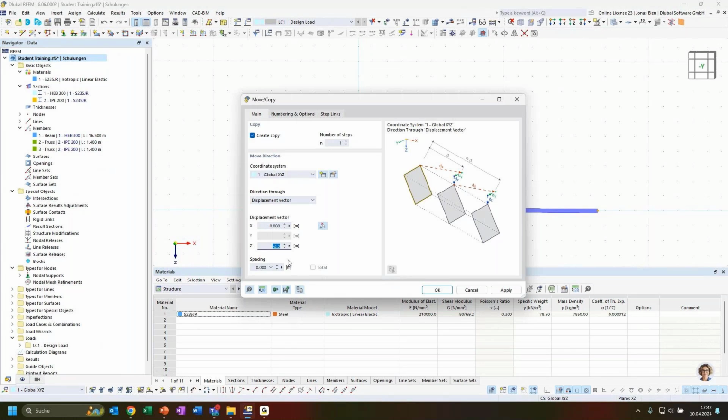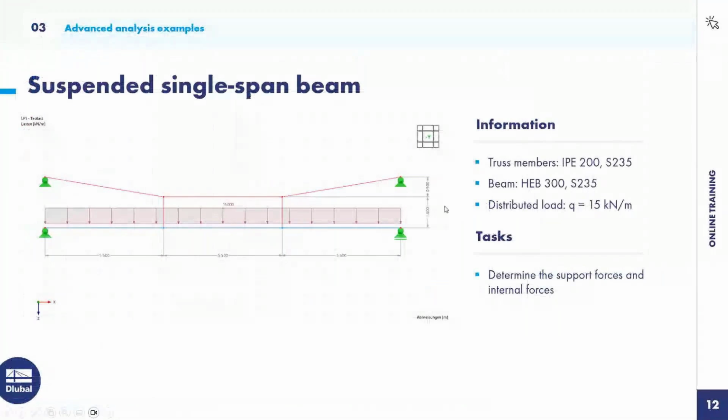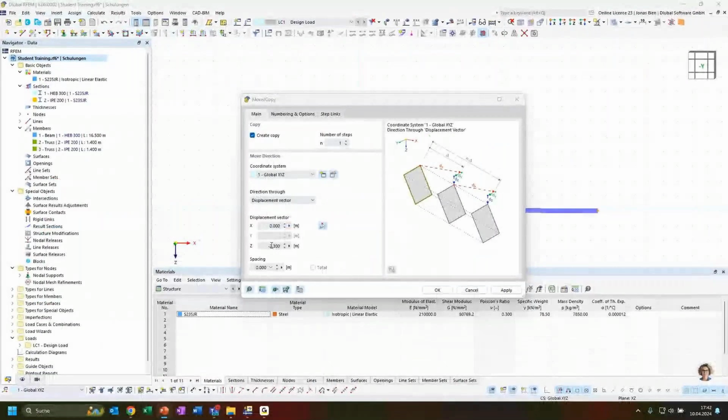I could also, if I have the dimensions like here in this PowerPoint presentation, where I have 1 meter 40 plus 0.9 meters, of course, I can calculate this in my head, but if the numbers are not that even or easy to sum, I can also type the mathematical operation in this input dialog, and it will calculate the correct value for me.